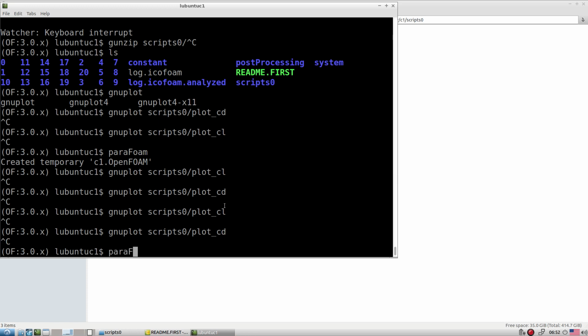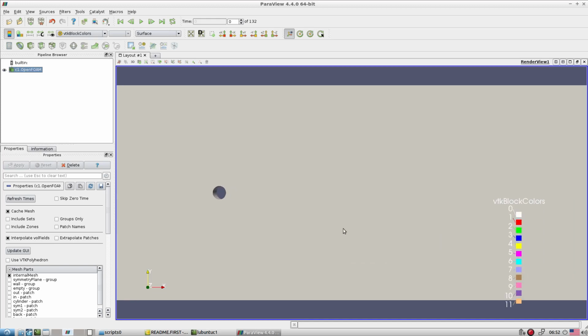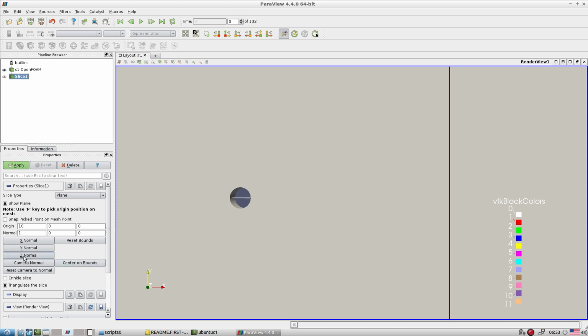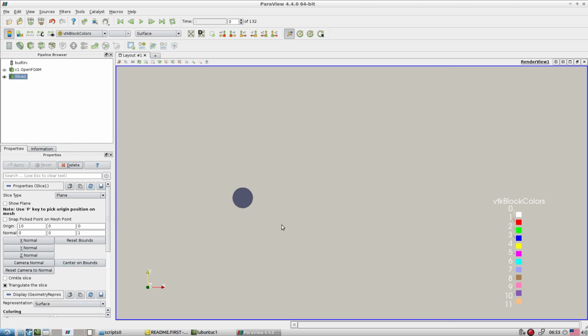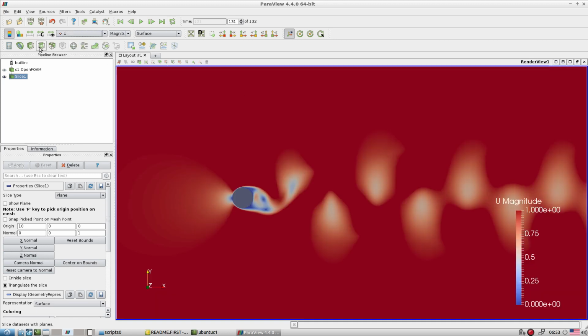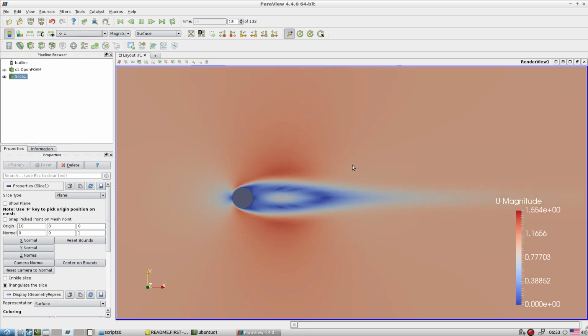Let me show you how the ParaView is progressing. Okay, so if you see the ParaView, let me zoom in on the area where we are interested. Let me cut the slice. Okay, here is the slice and this is the velocity. Let me go straight to the end, and what I did, I went here. Okay, so I reached the last slice and then rescaled the data, so based on that it will scale very nicely. Now come back to the first slice from here and then start the simulation, start the animation ultimately.